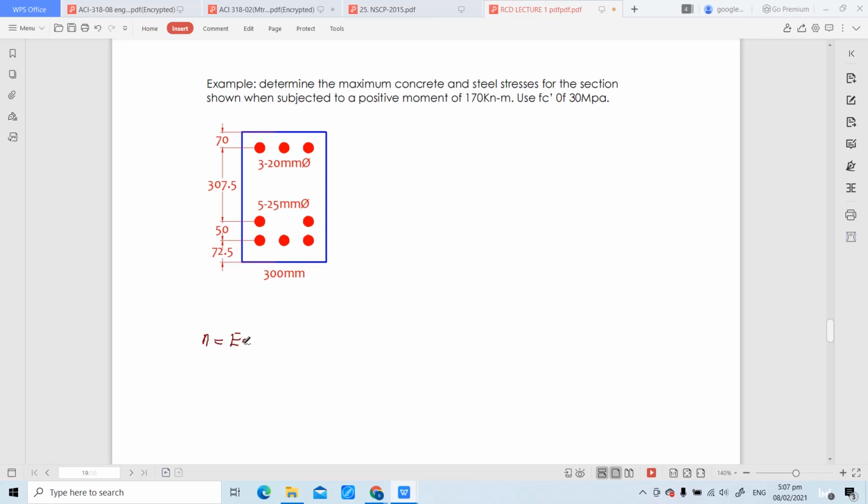And that is the ratio of the modulus of elasticity of steel with respect to the modulus of elasticity ng concrete. For the modulus of elasticity ng steel under prestressed reinforcement, that is constant, 200,000 megapascal. How about the modulus of elasticity ng concrete? Walang sinabing density ng concrete, therefore, you have to assume that it is a normal weight concrete. So, Ec is equivalent to 4,700 square root of f'c, that is 30, and naka-megapascal. So, cancelled yun. Kindly compute the value of n. 7.77. 8 po. 7.77 and round up to a whole number equivalent to 8.